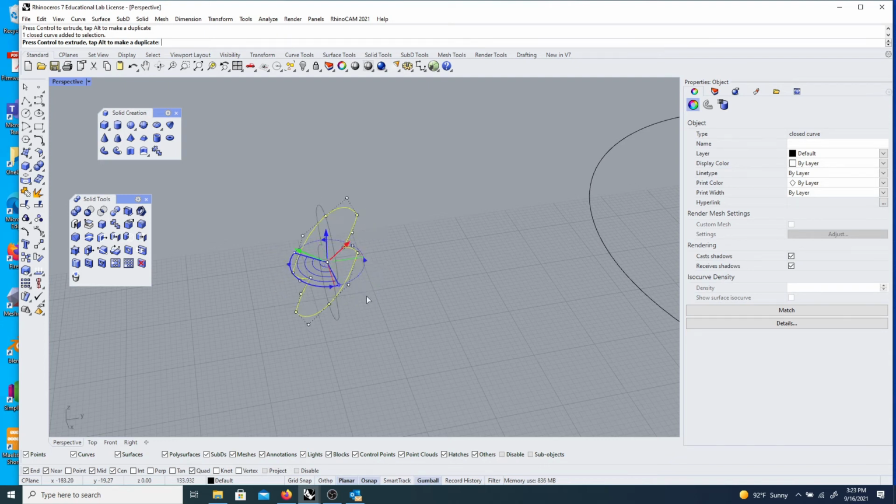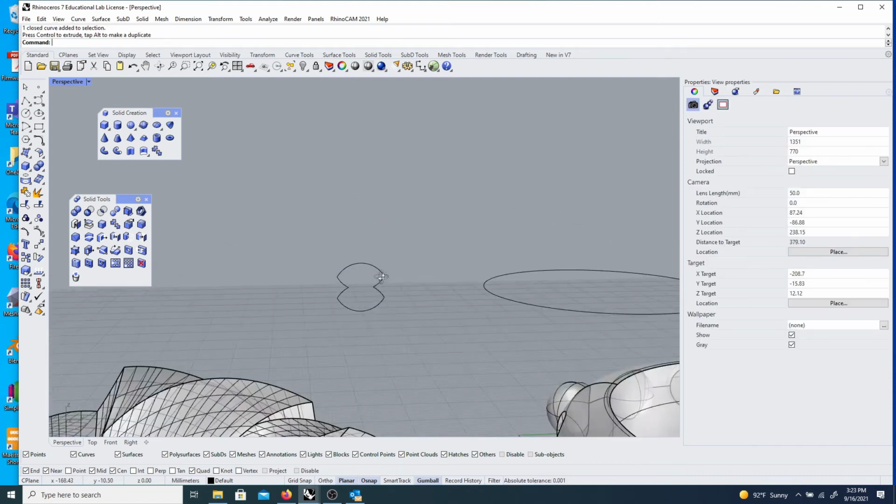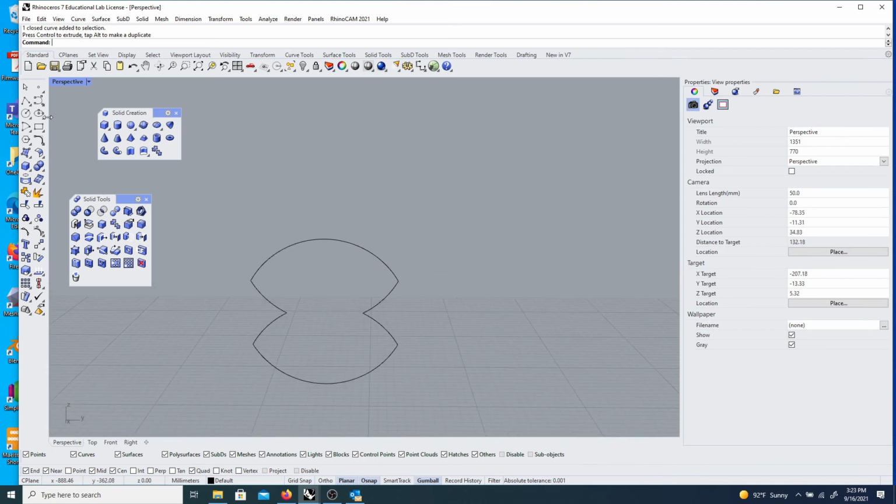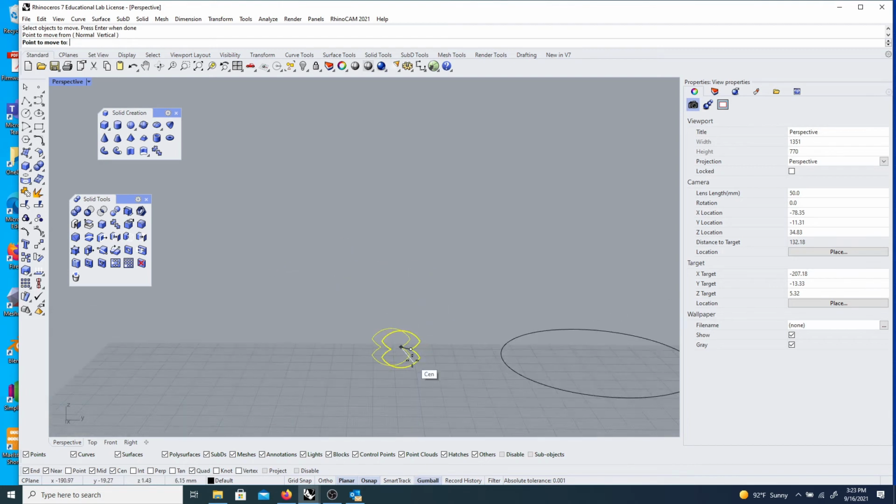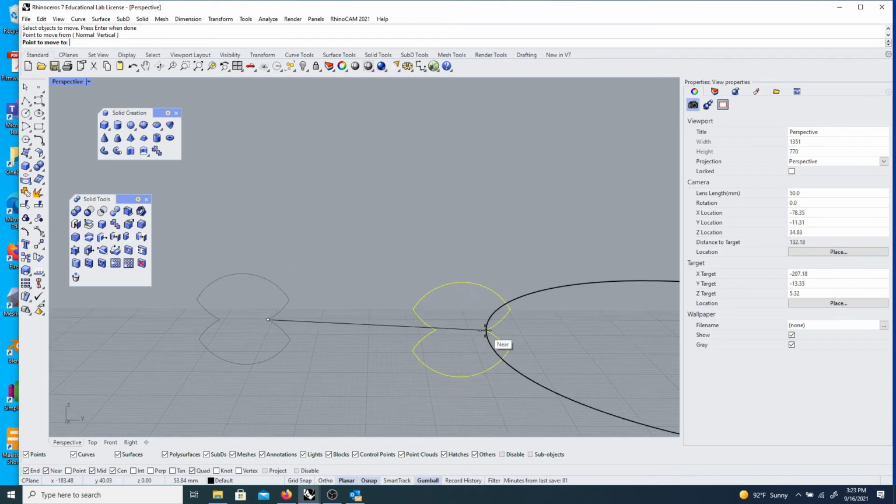That's the hotkey in most programs to snap to 90. Same in Rhino. And then I want to move it, so I can use a move command here. I can move from a specific point. I want to move this object from, we'll say, this point, and then move it to this quadrant or whatever.